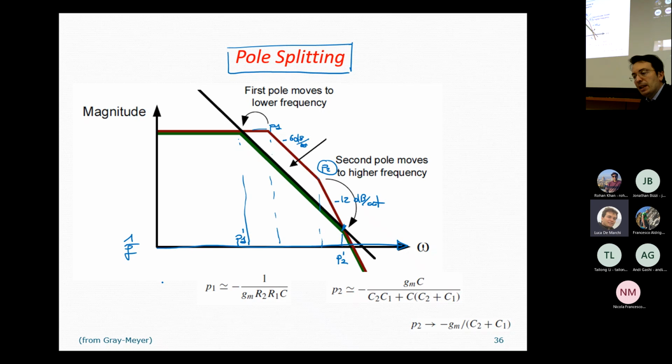Okay, so if we have this situation, then no current is flowing here, and all this current generated by transistor I5 flows into this branch. The current mirror duplicates the current input, so no current can flow even here. So I5 discharges this node.